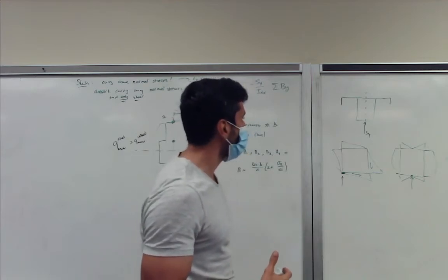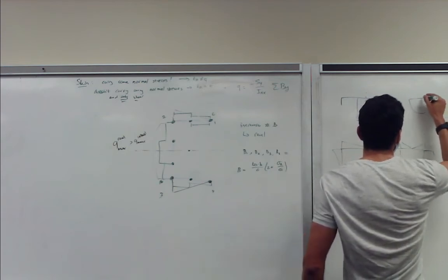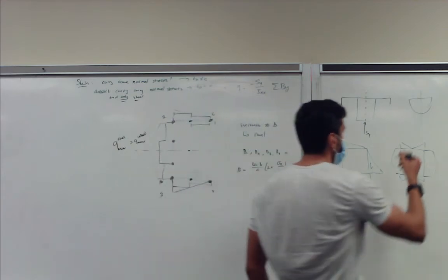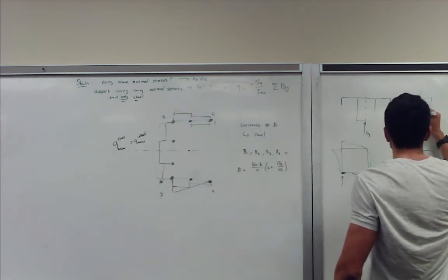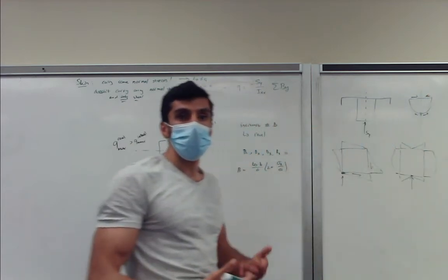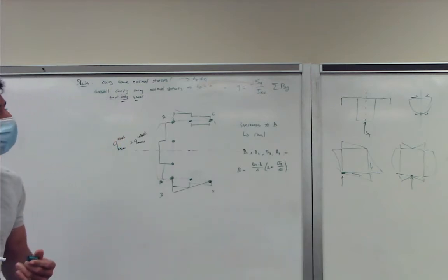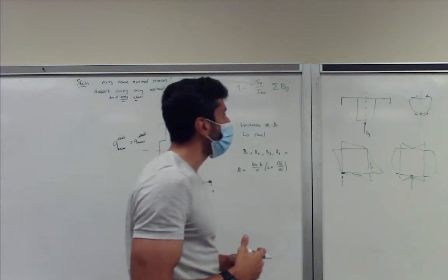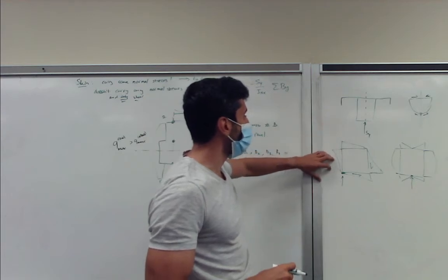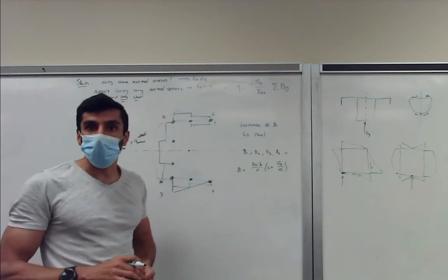So what I said again is, also in the exam, what you had was this shape, right? Just make the cut and draw how it looks. And you can often see if you can reduce the problem complexity or not. So that's always a good start. The second thing you always have to do is, by looking at it, realize if it's an open structure, a closed structure, or combined open/closed, because the solution approach will also vary on that.